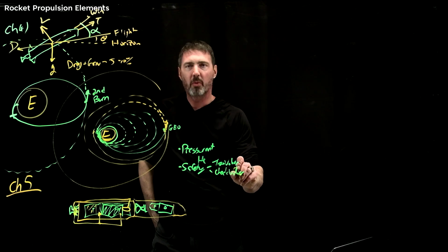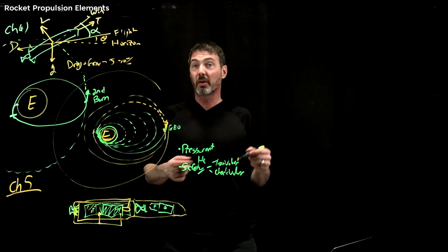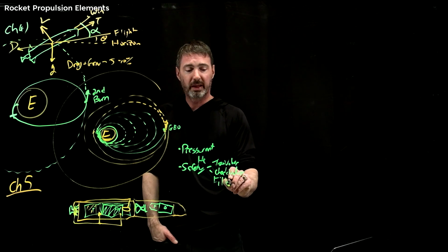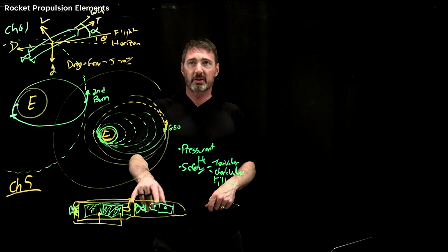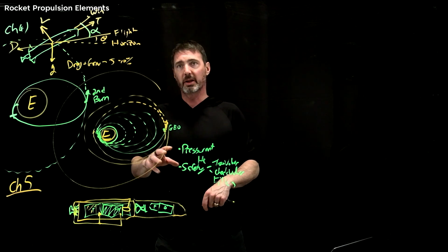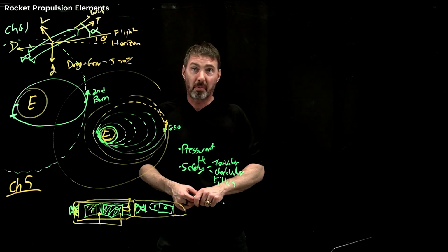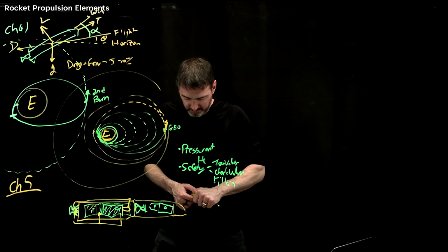What you absolutely don't want to have happen sometimes is you want your oxygen or fuel to go a certain direction, not others. So you have check valves, you have filters that have to be in those lines to make sure it's clean. If for some reason you got some junk into your ox tank or your fuel tank, you can't have it go and plug up something in your engine. Your engine may melt and rip apart if you have all that stuff. So there's a lot that goes into there. Okay.